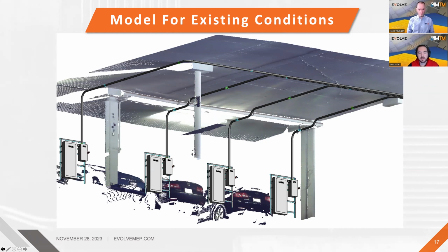But the scan is so much faster and so much easier. In this kind of case that I've mocked up, say if we were going to add EV charging stations into a parking deck, the point cloud that I created this from was only one scan. Ideally, you'd probably want to end up getting a few more. But when I was scanning, for the fidelity or the density of points that we needed, we could get away with 2-minute scans. So we could scan a large area very, very quickly.